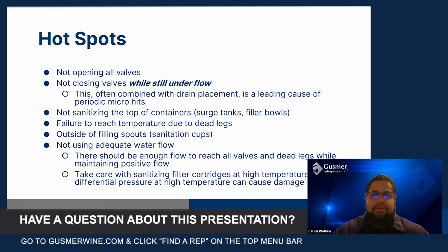So if you have long tees or spots in the winery where you think you're not getting the sanitation fluid, make sure to check them, and check the temperature in those spots.